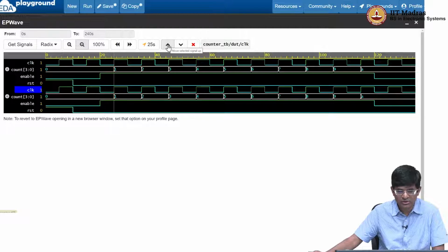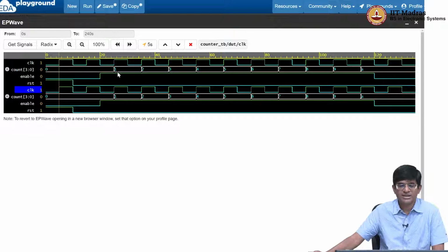I can also move the signals around in various ways, or I can look for various kinds of different patterns that get matched over here, right. So these are tools that are generally available to you for examining the outputs generated by a test bench, and can be very useful in terms of debugging whether something is changing the way you expect or not. Okay.